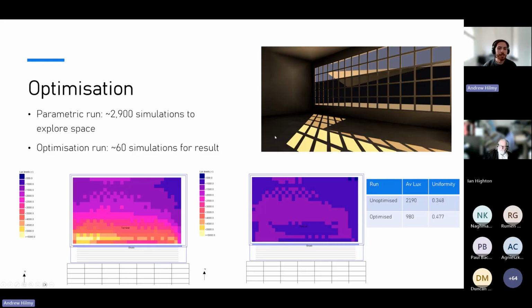And the interesting thing is, if you did that same simulation without varying each row of windows' transmittance as a variable, then the best result is actually a shade angle of 90 degrees, which is basically just a solid overhang rather than having a nice angle there.